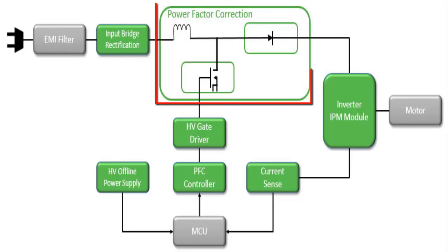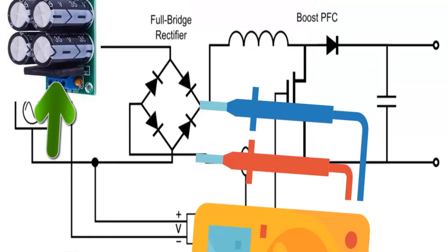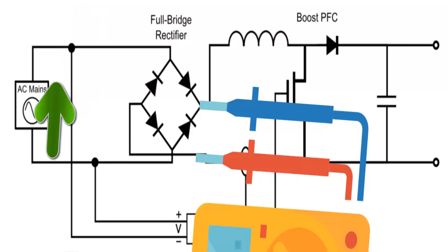6. When the LEDs do not light up, to verify the PFC circuit, ensure that the continuous voltage appears within the card, especially at the output voltage of the PFC rectifier bridge. When the equipment is powered with 110 volts AC, after the rectifier bridge, the voltage should be around 150 continuous volts, and when the equipment is powered with 220 volts AC, after the rectifier bridge, it should be around 300 continuous volts.